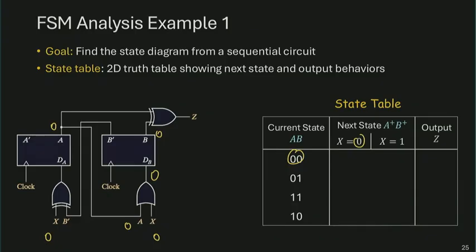The XOR gate produces a 1, which means if my current state is 0 0, which sits at the output of the flip-flop, and my input is a 0, the next D input will be 1 0, which means when you're at the next positive edge of the clock, the state will be updated to 1 0. And therefore, this is 1 0.